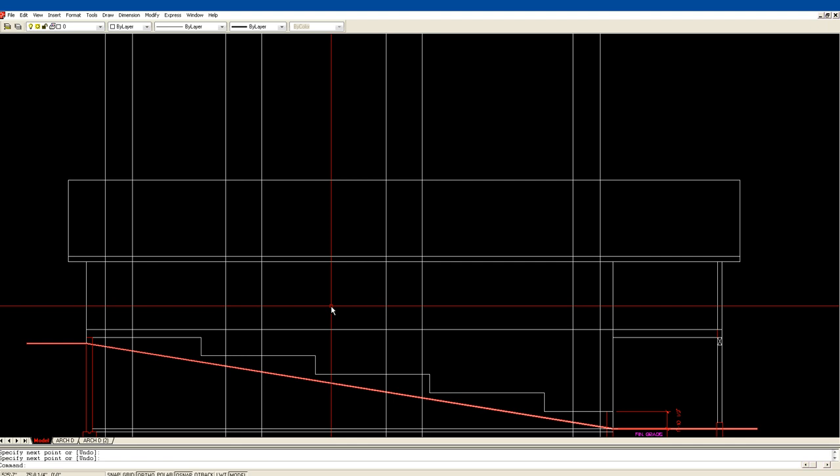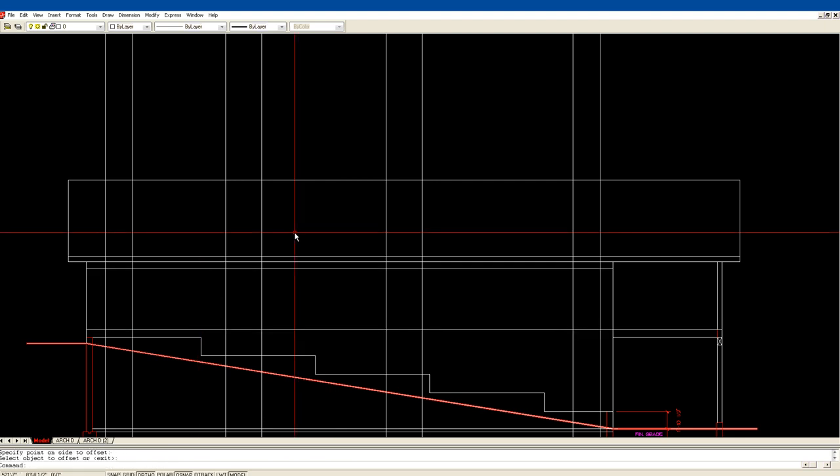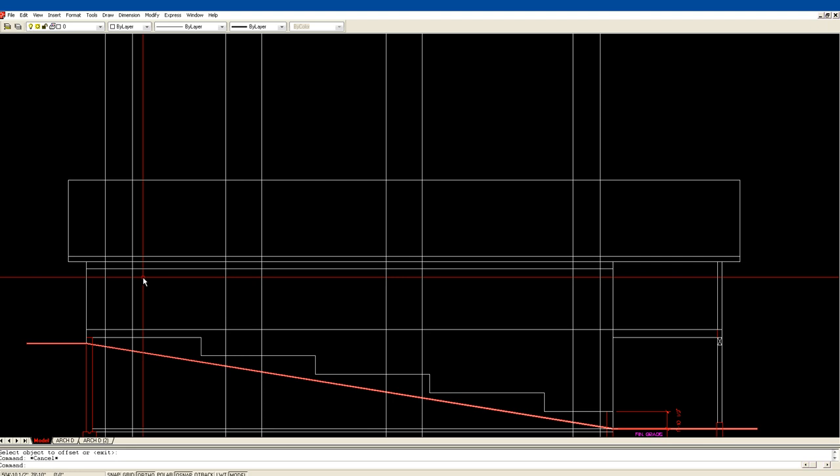So that's 9.5 inches plus the 3 for the plates. Plus at the bottom of the header, if you nail 2 2x10s together, it's only 3 inches, but our walls are 6. And so you usually put a plate on the bottom, so that would add another 1.5 inches. So typically it's 14 inches down from the top of the wall, or 80 inches up from the bottom. In this case we're just going to use 80. So that'll be the same height as the top of our doors. There's 80 inches.